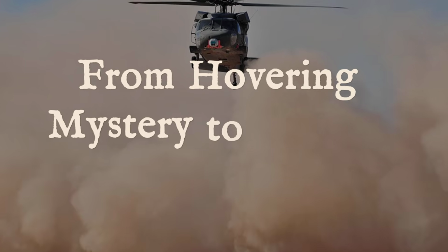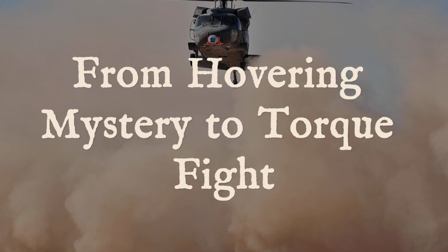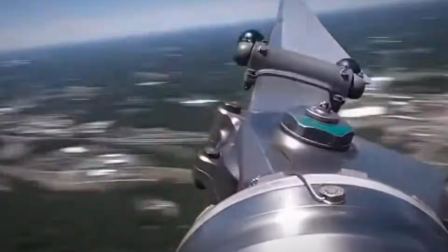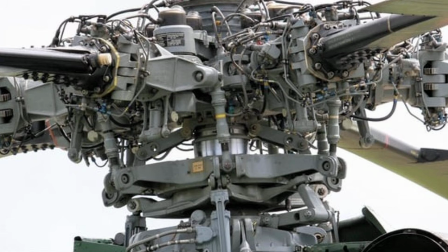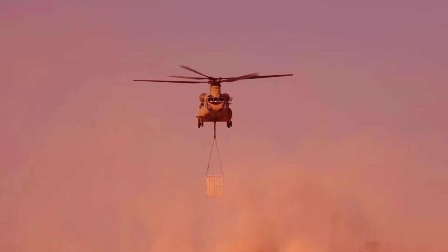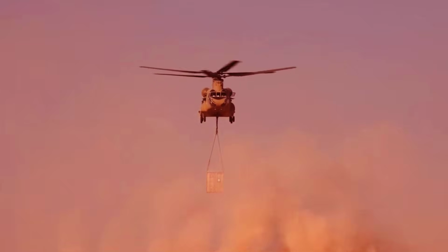of it. A helicopter in hover creates its own wind, forcing air downward through the spinning rotor disc to keep itself aloft. Each blade, thin and fast, sweeps out a circle that acts as a self-powered lifting surface. This is not just a wing in motion. It is a machine generating its own pressure difference, building lift from rotation alone.